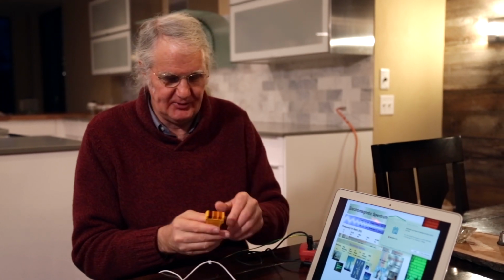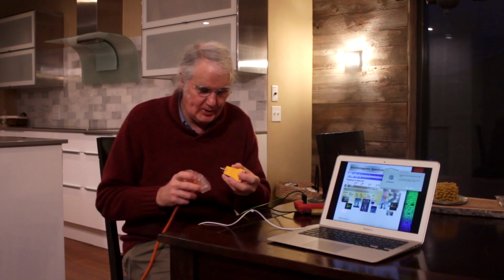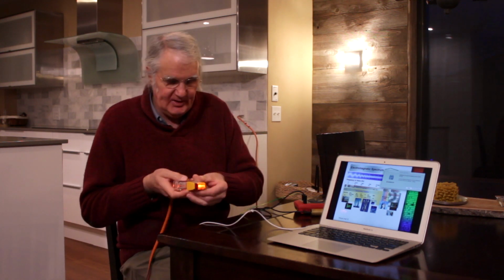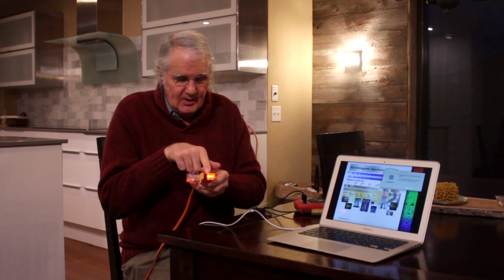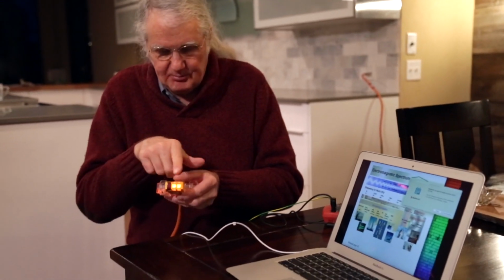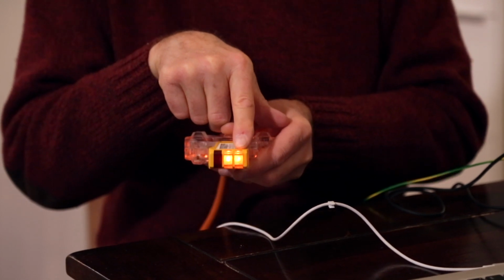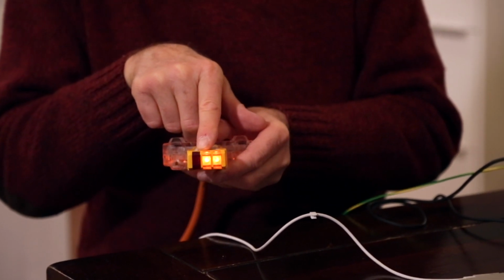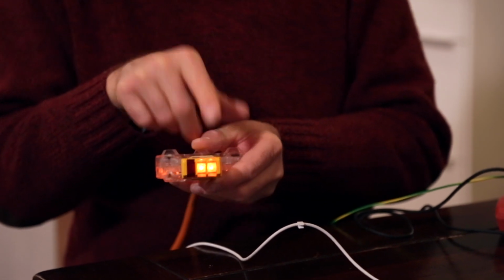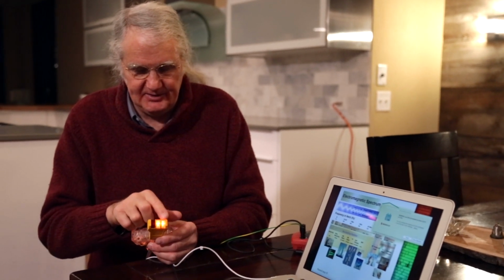So of course, you're all familiar with the use of circuit testers. And what you need to see, as I can show you here, the proper configuration that we want you to see from an EMF standpoint is this, where the center light is lit, meaning that the circuit breaker is on, and that there's 120 volts here, but that this ground indicator here, the second yellow light, needs to be lit and as bright as the center light. And if it's dim, then it's loose and it's as if it was not there. So that needs to be fully grounded in order to avoid the electric field exposure.